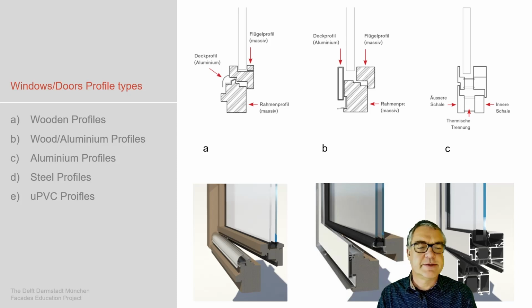within the profile. So all the functionality which we expect from a facade, being airtight at the inside, being raintight at the outside, and having this function zone which insulates in between, that all has to happen within this profile, but also when it is opened, with all the sealant which tightens this window, that has to happen in the same setup. Then the second one, an aluminium profile.